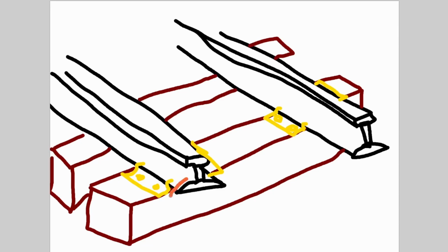A rail anchor typically looks something along the lines like this. It clips around the foot of the rail and sticks up on the other side typically. And what it does is it prevents the rail from moving longitudinally down the track or up the track because the anchor will rest against the side of the tie. And so that anchor will prevent the rail from moving.